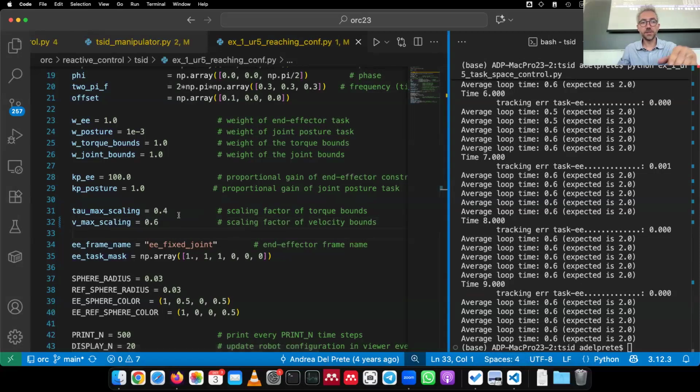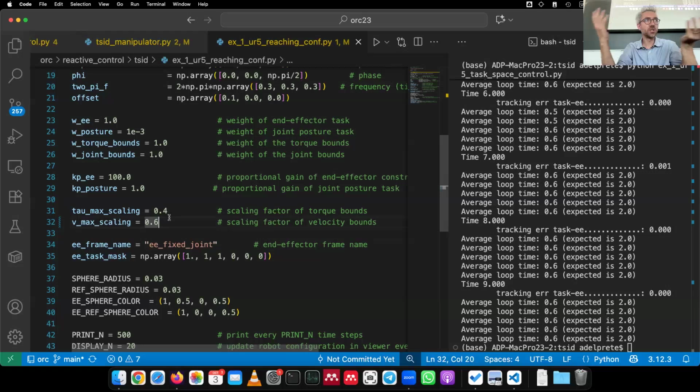That being said, if those were our real joint velocity limits, there was nothing we could do to fix it. Here we just tested the hypothesis by increasing the joint limits, but you cannot do that on a real system.